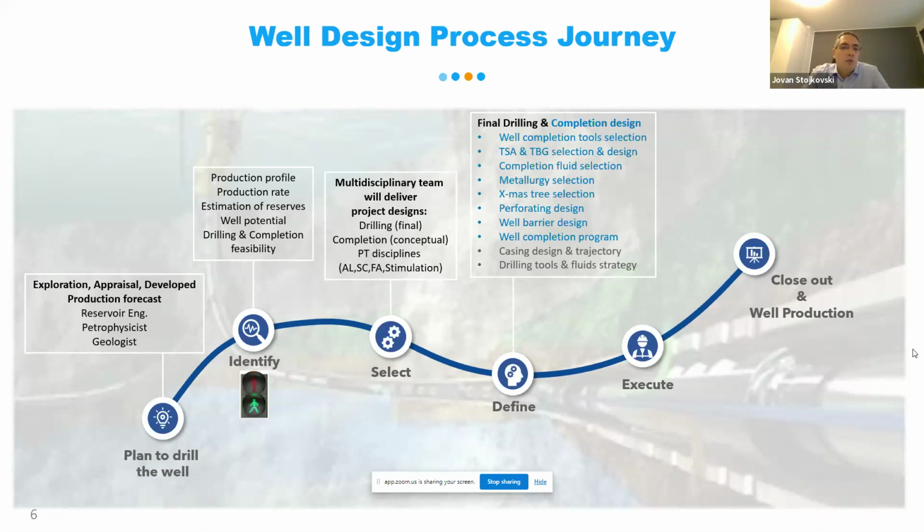Basically, he needs to deliver tubing, jewelry, packer, and completion tools which will work together for different scenarios over the well life. So when he designs the completion, he is not looking only at the production phase. He is looking at a potential acidizing job, potential injection job, killing the well, leak occasions, and so on. There are many other scenarios which he needs to include in his design to see if the whole system will work under different circumstances.